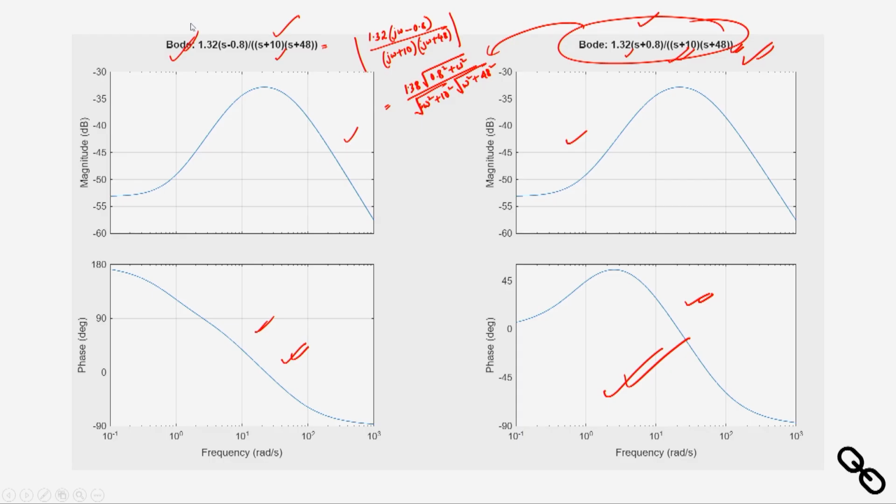So with one example, I have shown you how to do it experimentally, as in how to find the magnitude and phase plots. You find the magnitude and phase plot somehow, and then you go ahead and do this analysis. You can find the transfer function of the system. What you have to do is take the magnitude plot, try to fit an approximate Bode plot on it, and then find the transfer function of the system.